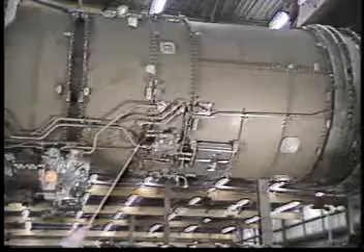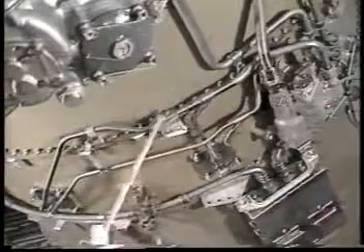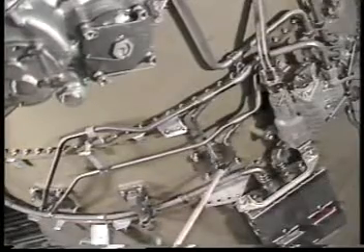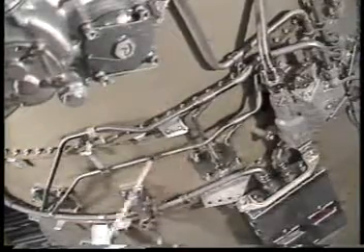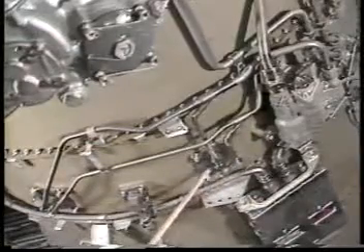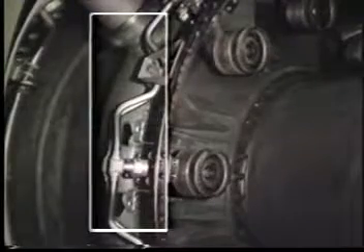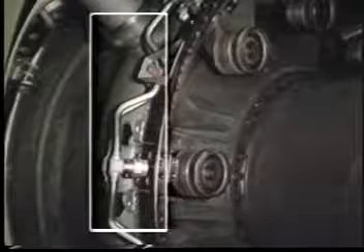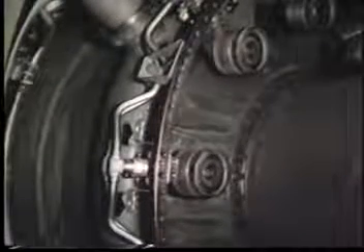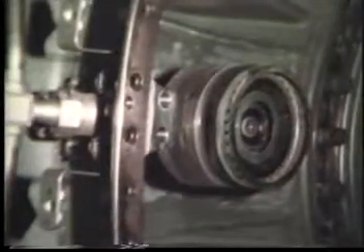The fuel flows through the external manifolds located under the engine, outside of the fan discharge diffuser duct. Internal manifolds then distribute the fuel to 9 of these fuel nozzles. Here, it is atomized and aerated for combustion.